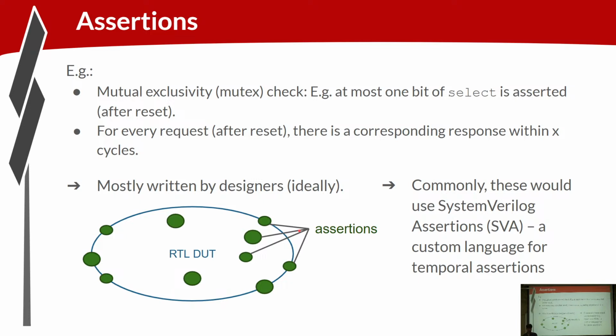You'd be surprised how many situations like this, you sort of think, okay, well, these are mutually exclusive. That's guaranteed by the logic, but something's going to happen somewhere along the way that breaks that. And if your error message is these signals are mutually exclusive, versus the value in this register is wrong, right? It's a lot easier to debug.